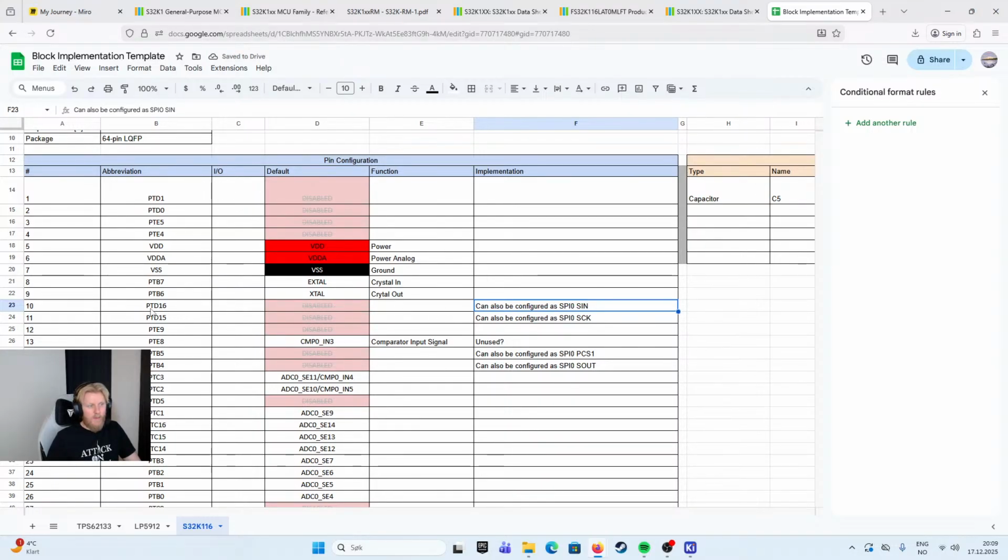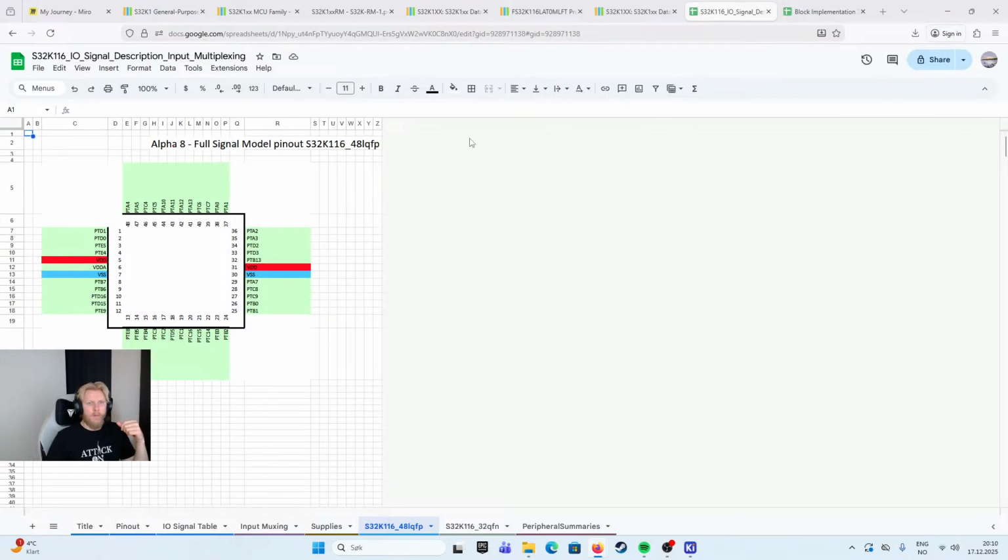So pin 10 to 15. And then I can check on the 10 to 15, that's right at the corner of this package. So I'll show it here as well. 10 to 15 here. Meaning if we have some device down here, we can optimize our pinout so that it makes it easier for us during the layout.